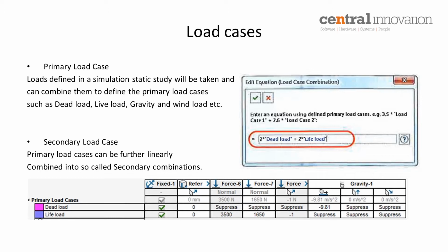That is the main purpose of load cases. Let's say you have a design and you want to test it for multiple design scenarios, and you want to combine the design scenarios or loading scenarios and see the results. This is the tool you can use, load case manager. I'll show an example, and you can ask me a question like, how do I track the results?